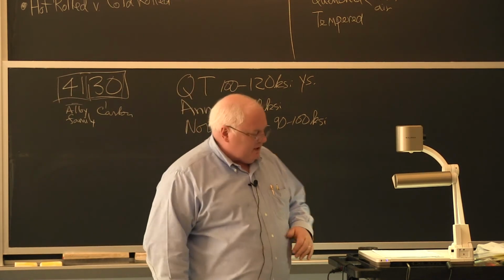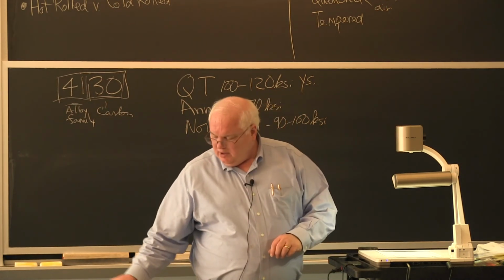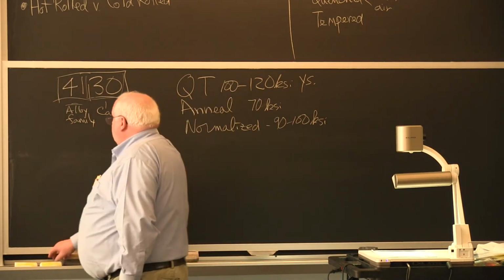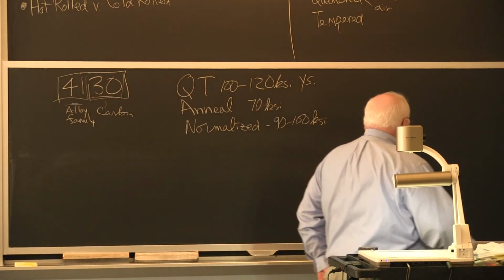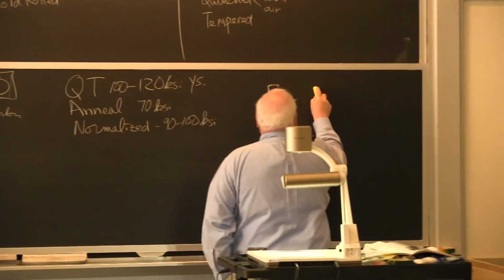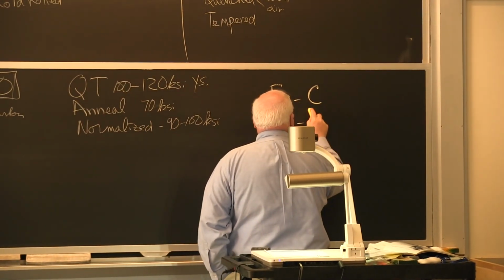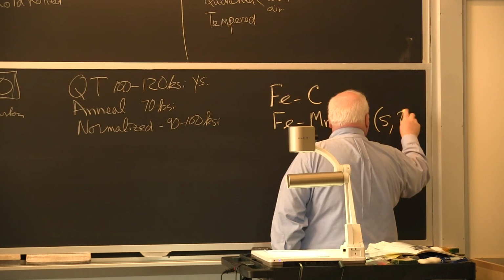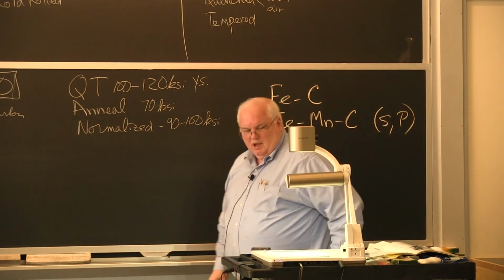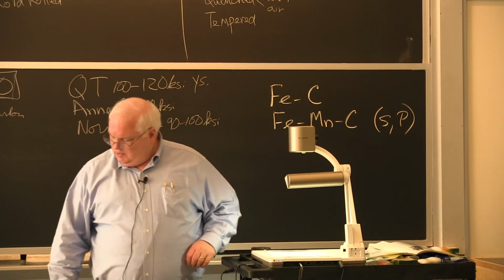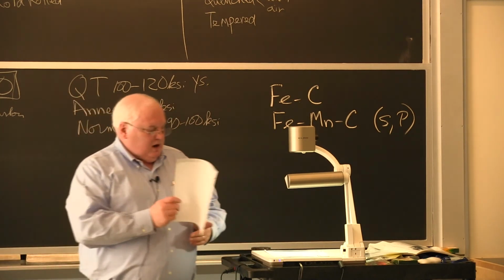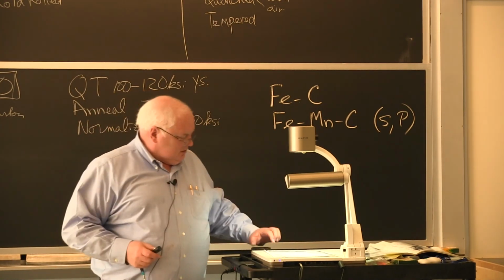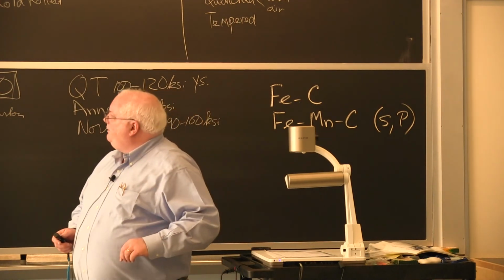Let's go into some of the other things on steels. We did talk about, or there were some questions about, the composition of steels. I said steel is an alloy of iron and carbon. Iron and carbon, and we talked about how you need manganese. You need manganese to tie up the sulfur, because you always have some sulfur and phosphorus impurity. And what I did is I brought the manganese phase diagram for all of you phase diagram buffs, if I can get it to show.